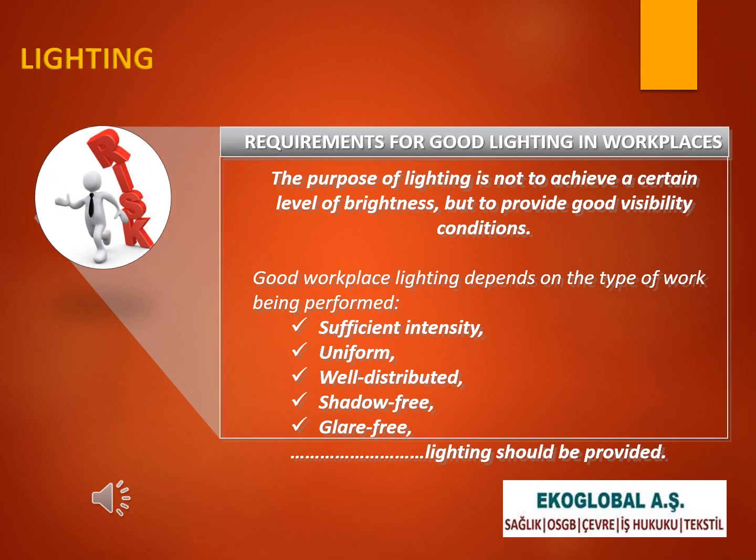Requirements for good lighting in workplaces. The purpose of lighting is not to achieve a certain level of brightness, but to provide good visibility conditions. Good workplace lighting depends on the type of work being performed. Sufficient intensity, uniform, well distributed, shadow-free, glare-free.